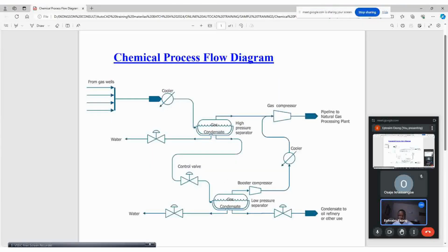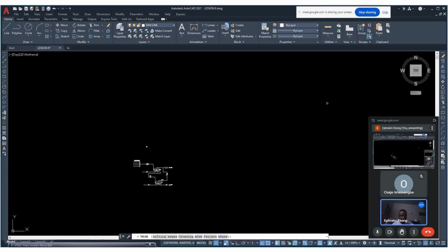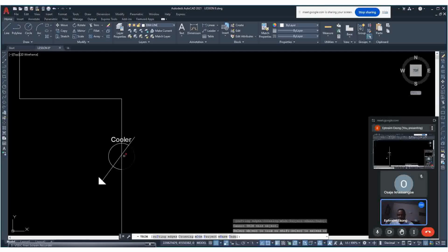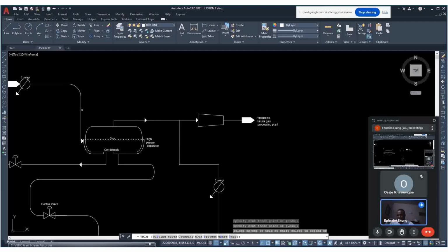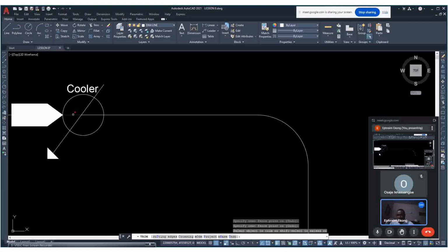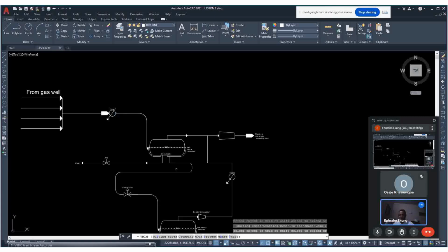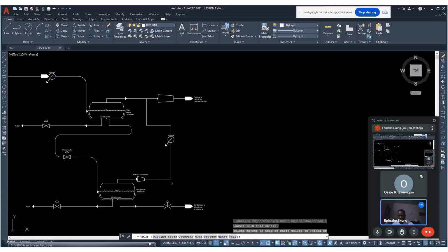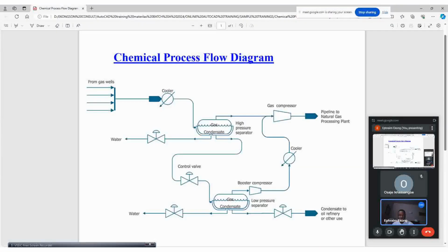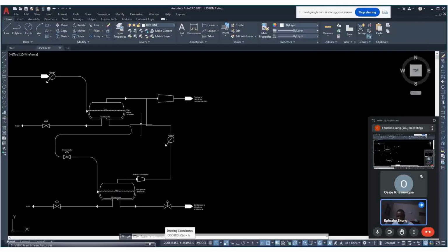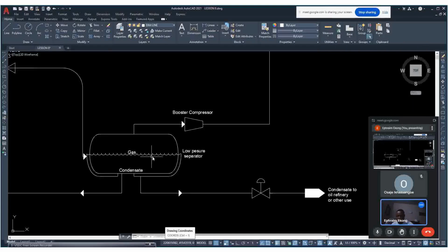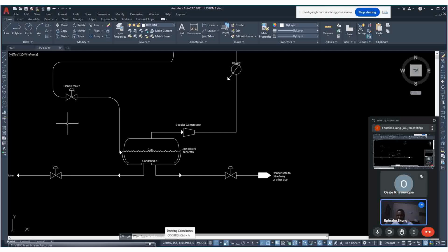Okay, go to trim, enter, trim this one off. Likewise here, trim it off. We don't need it. Escape to end your command. What next? Your arrows. Okay, arrow up. So look for an arrow that is going up. None that is going up.